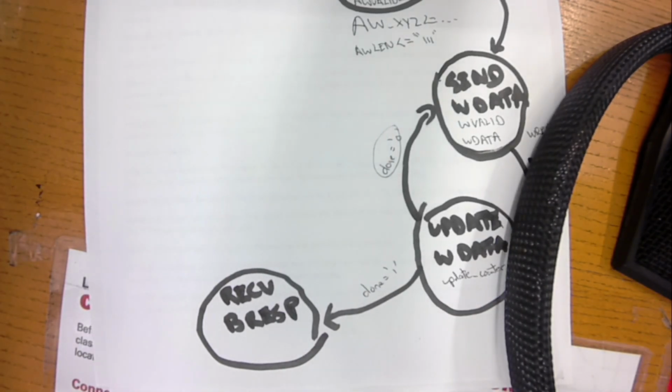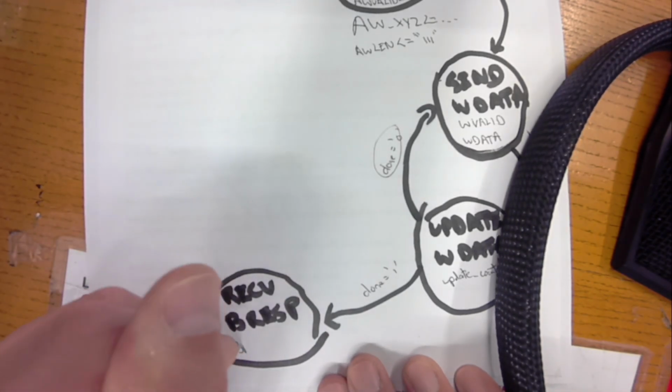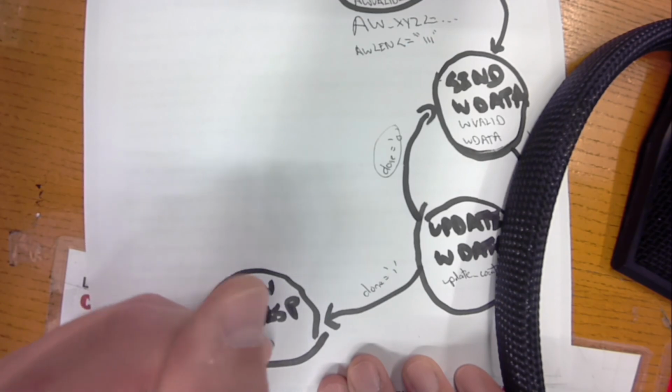Where now I was the initiator, I was initiating the transaction, I sent the control signals, I sent the data, but now I'm kind of the receiver in terms of having received something valid from the write response here. Here I am then sending that I am ready for that signal. I'm the one sending this.